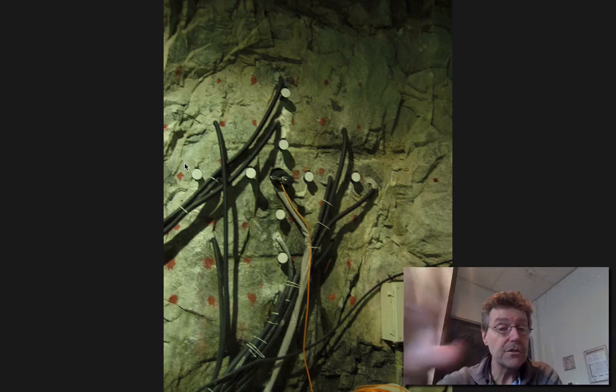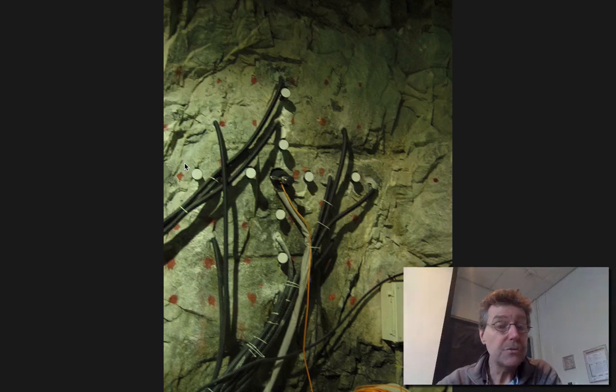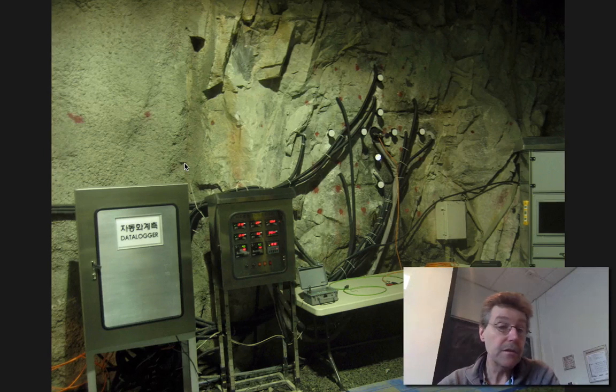And so this is a tunnel that's driven into a mountain and then instrumented to do things like tracer tests, where you inject a tracer into the ground and you measure its arrival in different places, measure stresses, measure how permeabilities change as a function of stresses, because when you put hot waste into the ground, it heats up the ground and it stresses the rock, and it may change permeabilities.